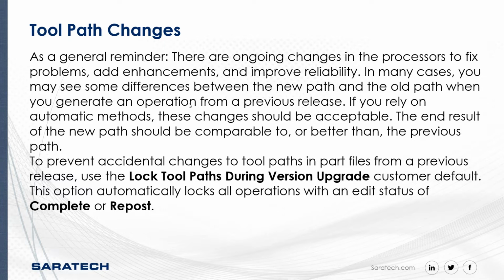And this is just a reminder, anytime you update NX, if you have programs that you've been running for months or years that you definitely do not want changed, there's an option inside NX in the customer defaults to lock the toolpaths during version upgrade. Any changes should be better, but if you know for sure that it's good the way you want it and you don't want it changed, you should lock them.